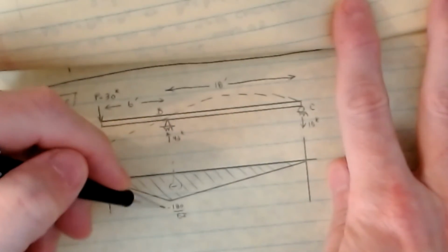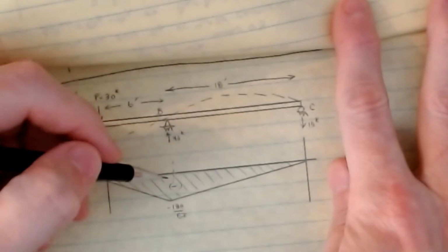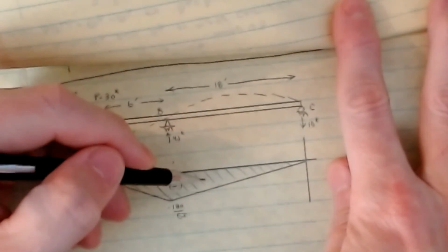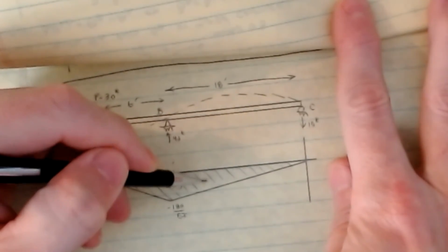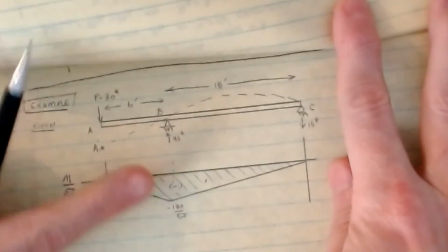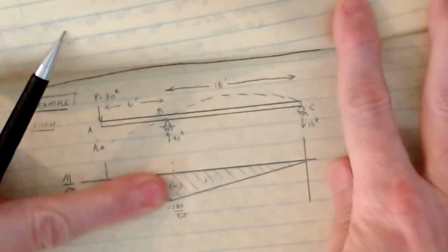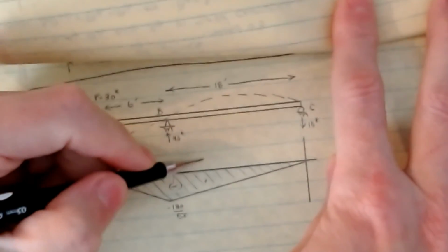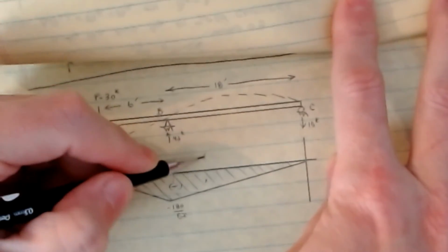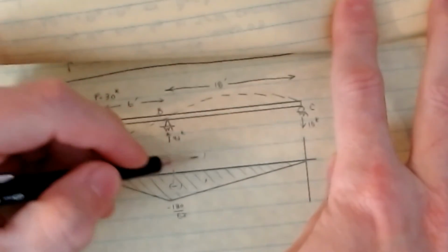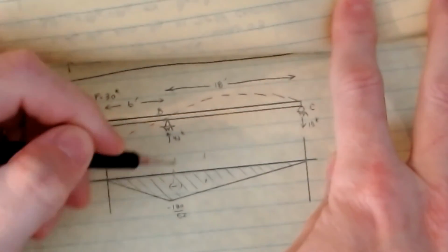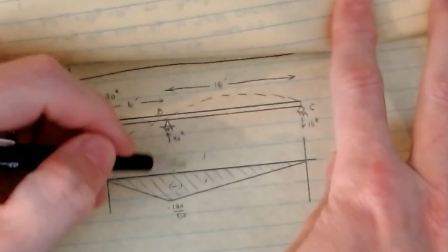And so minus 180 over EI, times a half times 18 feet will get me that area. And then the centroid, if that point is here, again, we're completely neglecting that side of it because I only need between B and C according to the theorem. Then this becomes the x bar that we're looking for. And if that's 18 feet, then this is 1/3 of that span, because it's 1/3 of the length to the high end for a triangle. Okay, and so that ends up only being 6 feet.